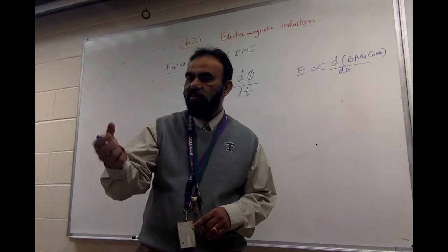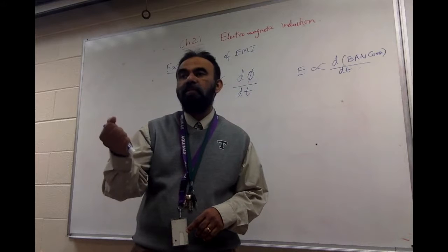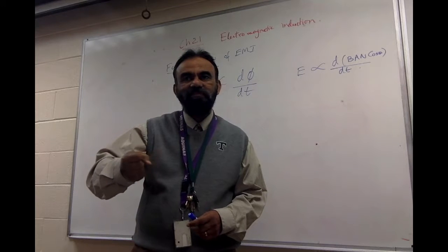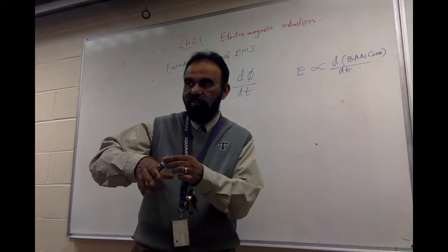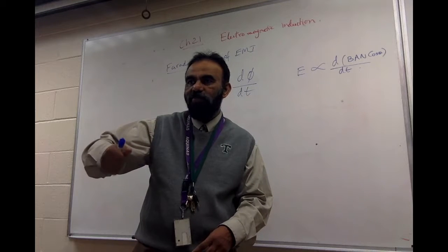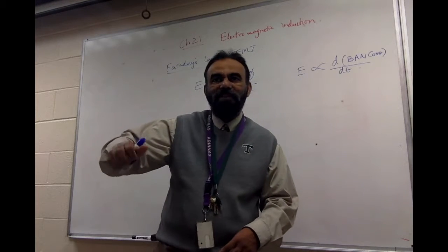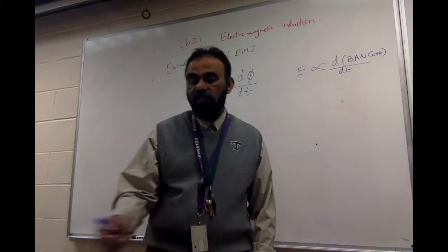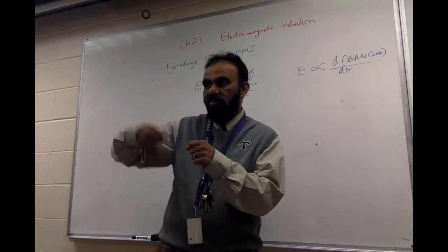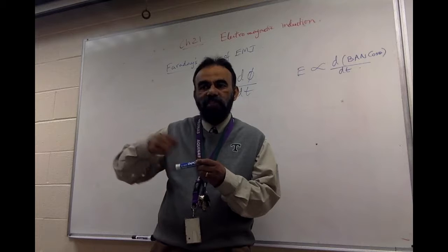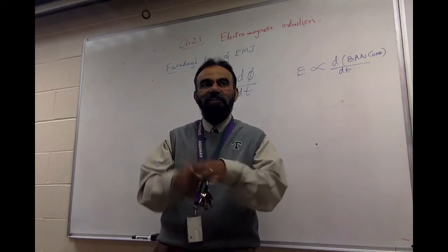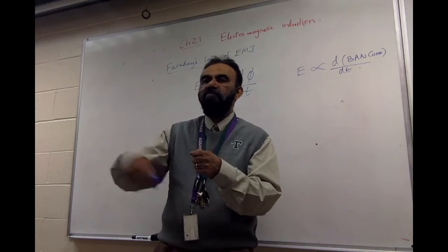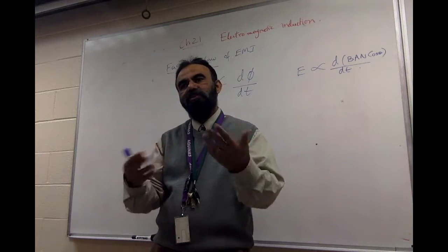And some of them, you're basically spinning the magnet by a squeezing action, like a flashlight that's got a lever. You pump it and you can hear it spinning. So those are all dynamos basically. Same with crank radios. What you're doing by cranking is generating the EMF to charge the battery, and after cranking for some time, you have enough charge stored. It is going to give you the energy.